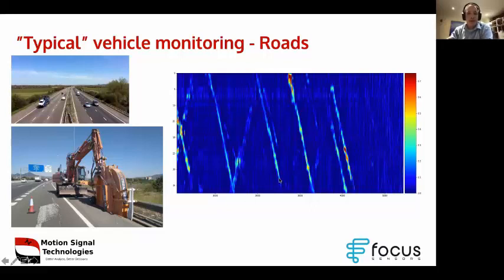And so the plot on the right here is a fairly simple intensity-based plot from a DAS recording. You've got the time axis going down the vertical axis and channel number going across the side. So if you like, this is distance down the road on the horizontal axis, and this is time going down here. And what you're seeing with these bright signals is the cars and trucks going down this freeway in a fairly short period of time. You can see there's quite a few different vehicles in there. There are ones with fairly common slopes. The brighter ones tend to be these ones that are sloping right here, and so that is probably the nearer lane. And you've got ones that slope the other way, which indicates they're obviously going the other way along the road.